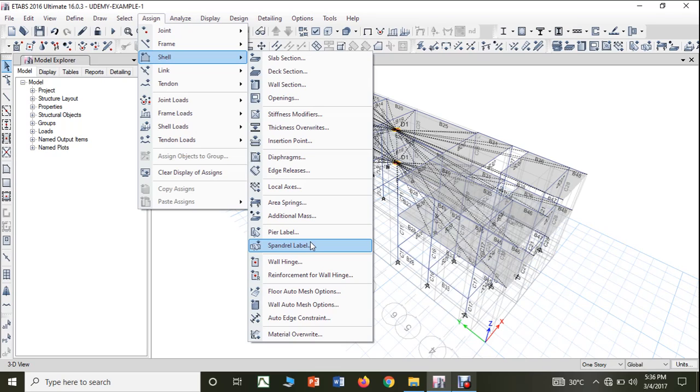So furthermore the load is not going to be taken. So at that time you have to make sure that there will not be any increment in the load. That is what we call the hinge formation. Okay, that is present only in the steel, not in the RCC. In the RCC the hinges will not be formed.